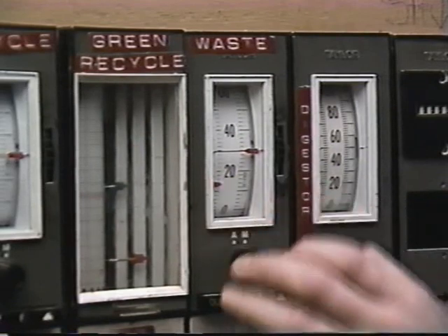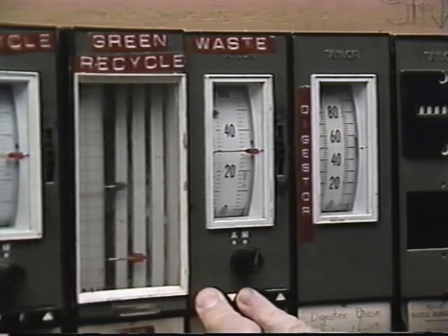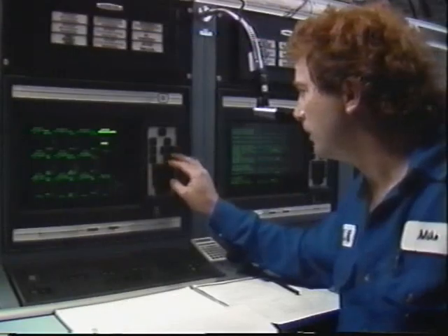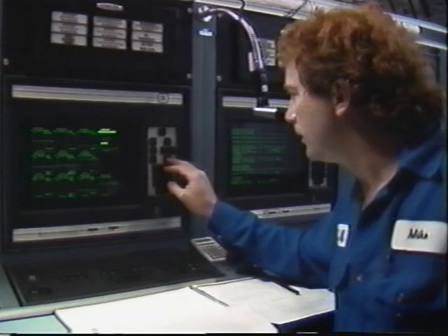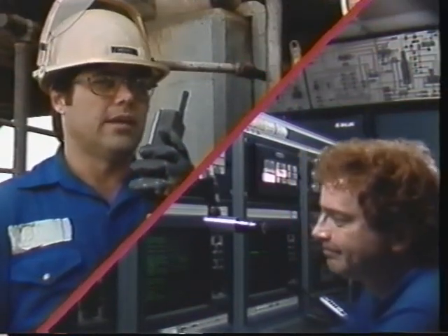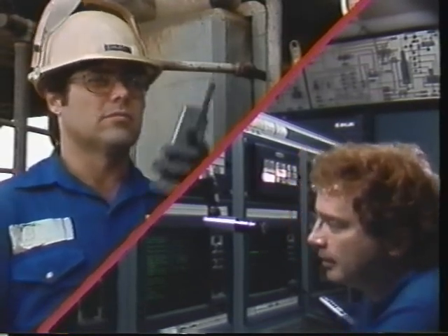Also, if the process was switched from automatic to manual control, when the problem is taken care of, it will need to be switched back to automatic. If the upset has affected other processes or units in the plant, you have to let them know that things are back to normal, so they can make adjustments at their end if necessary.